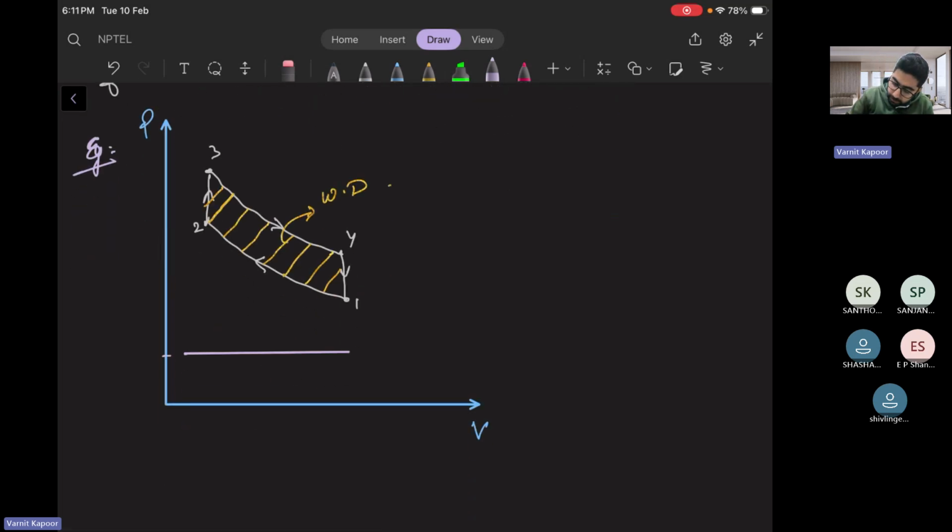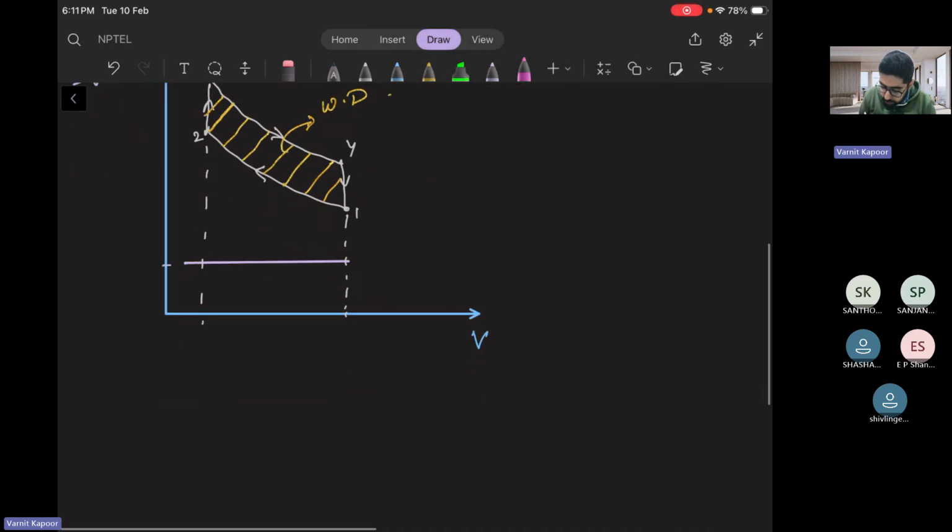So for an Otto cycle, what is the volume change? If you see, for an Otto cycle, the volume changes from this to this. So the volume change for this mathematical expression will also be from this to this. Let us use another color. So this was your swept volume overall, Vs swept. The constant pressure area under the graph will produce the same amount of work for the same volume displaced, that is your swept volume.